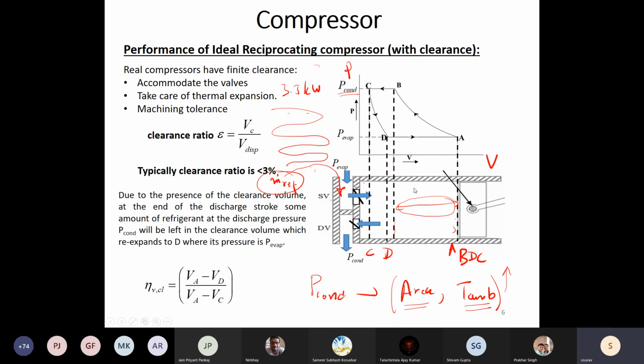Now suppose you attach a compressor which can deliver a significantly higher mass flow rate than what you are generating inside the evaporator. Then the issue you are describing will happen: your evaporator pressure will go low because you have attached a very large compressor to a small evaporator.